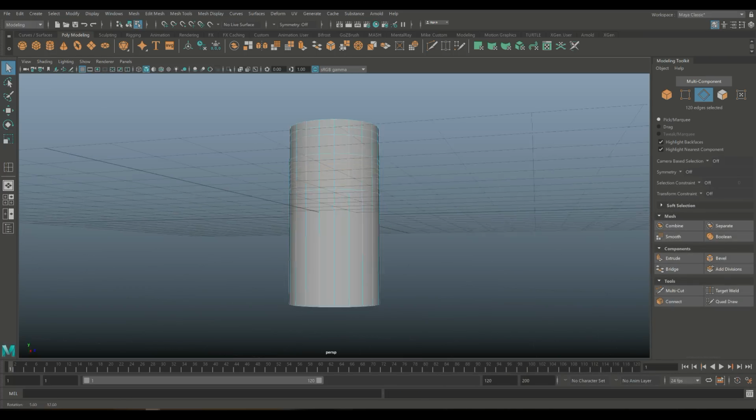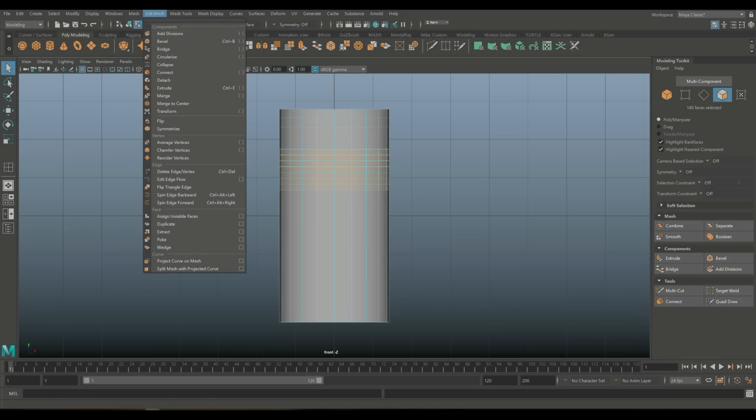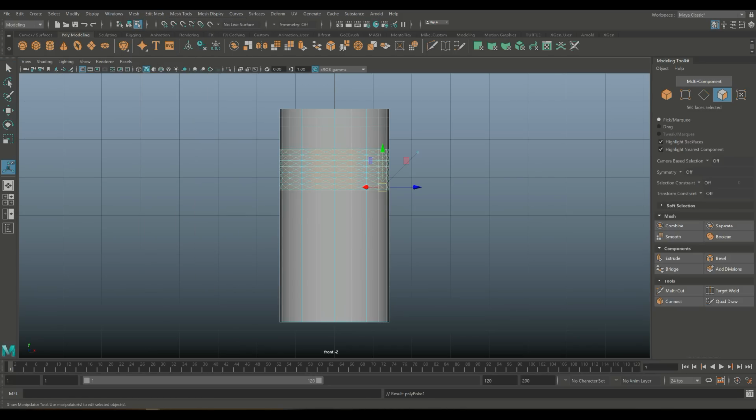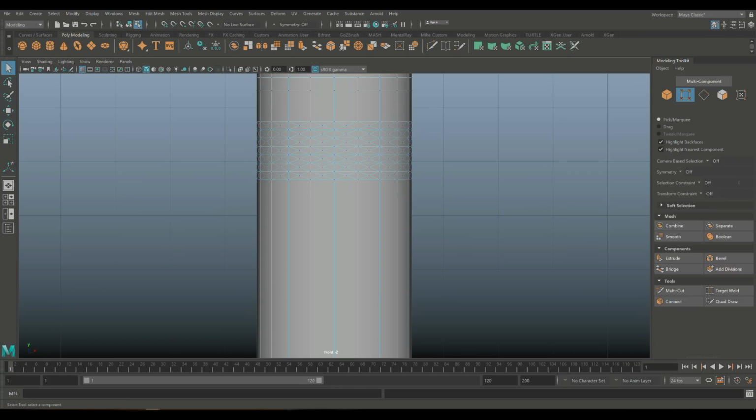So we're going to press Q on our keyboard, go back in, and select those faces: right click on a face, drag select all of them, and then go under Face to Poke, like this. Then we're going to go back in, right click on a vertex, and drag select the center vertices, and only those. Hold down shift for the next row, and just make sure you don't have the outer vertices selected like this, all right? So that's going okay so far. One more to go, like that.